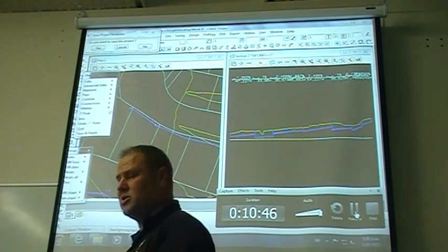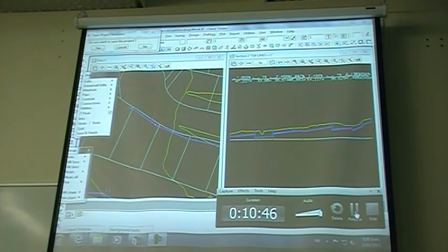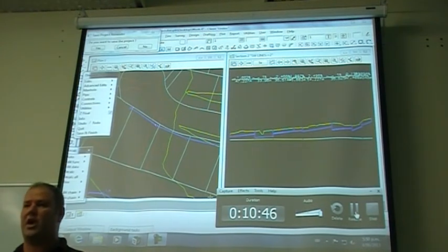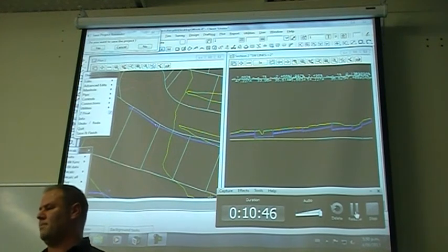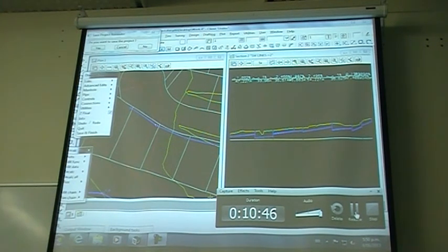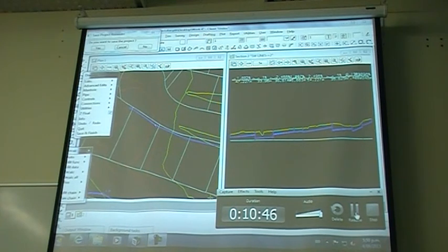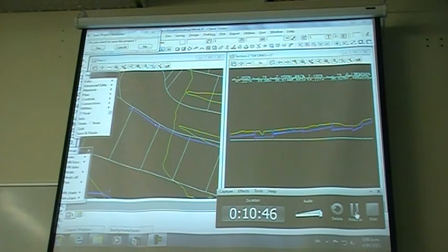with the placement, as I said, there are a few things you've got to think about when you start to place these manholes. The first thing you should be doing is looking at the contours and trying to work out where the lowest point on each of the sections is. What I normally do in the office is print off the scheme plan with the contours behind it, and I just mark a little cross in the corner of where the low points are.